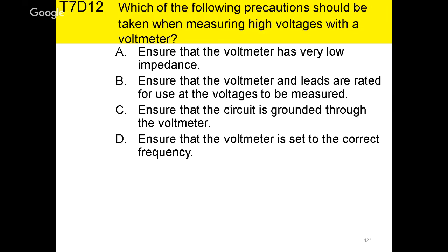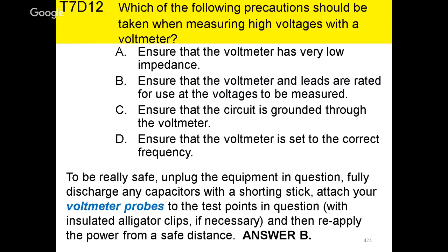Which of the following precautions should be taken when measuring high voltage with a voltmeter? We did kind of cover that, and your answer is B. You want to ensure that the voltmeter and leads are rated for use at the voltages to be measured.